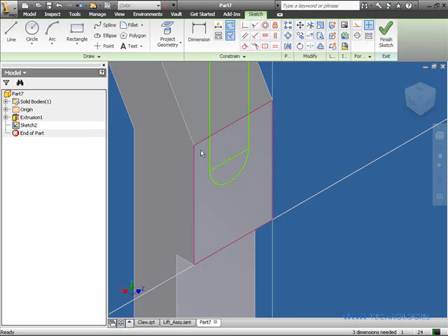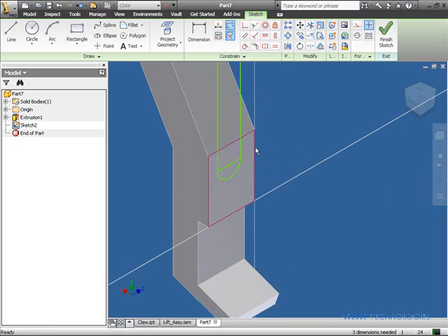I'm now going to center my extrusion or my feature here along this face. So I'll select the vertical constraint, my center point of my arc, and then the midpoint of that line right there. So now if I click and drag this, you'll see that it is fully constrained along the center. I now just have to add 2 dimensions to get it 100% constrained, as stated right here.